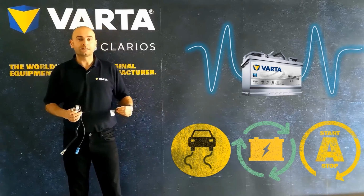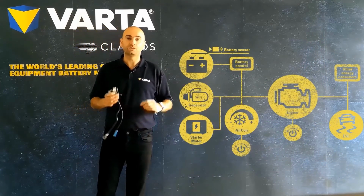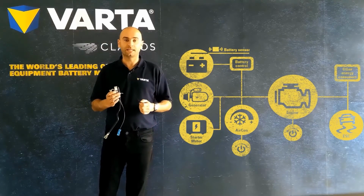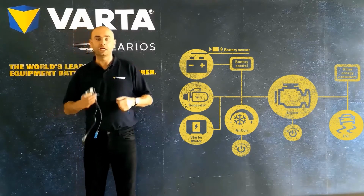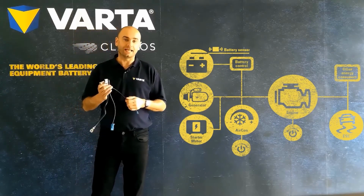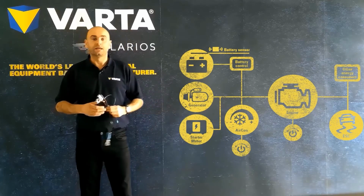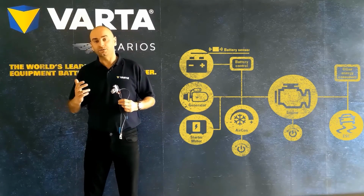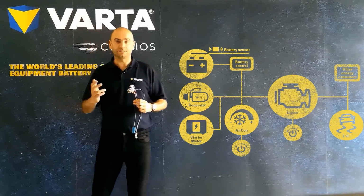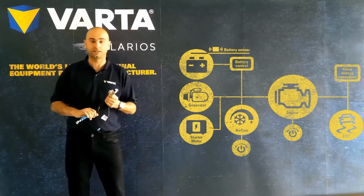The IBS sends data via a LIN bus to the vehicle's battery control module, which uses all the parameters to constantly calculate the level of charge to allow the vehicle to safely perform a stop, knowing it can start again and prevent the battery being excessively discharged. The system will also shut down systems that are classed as non-essential when needed to ensure safety systems have their allocated power when a system supply issue occurs.